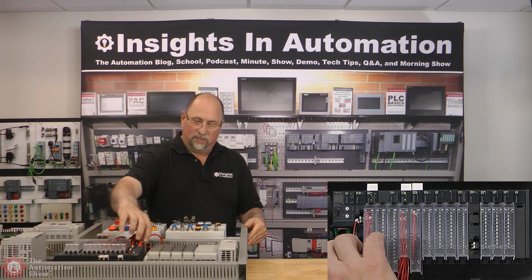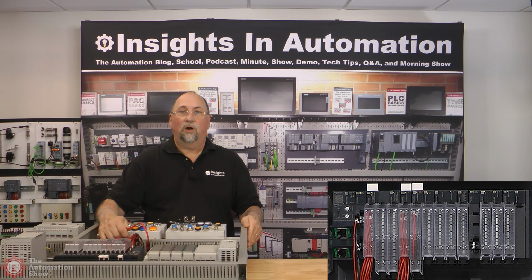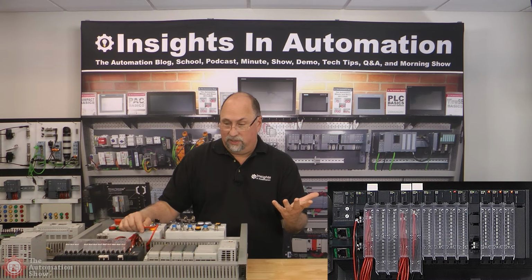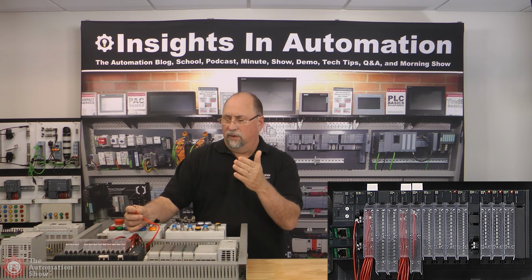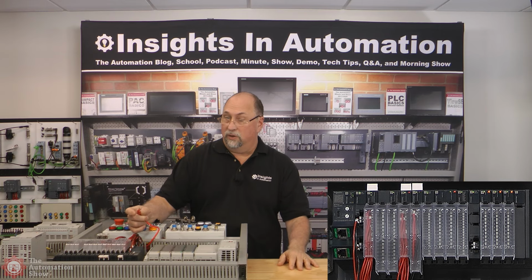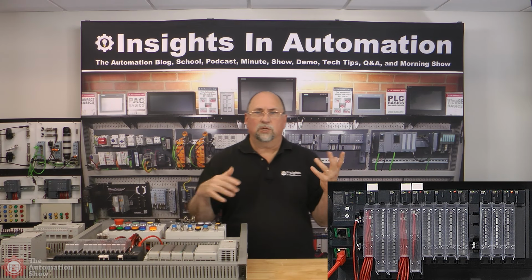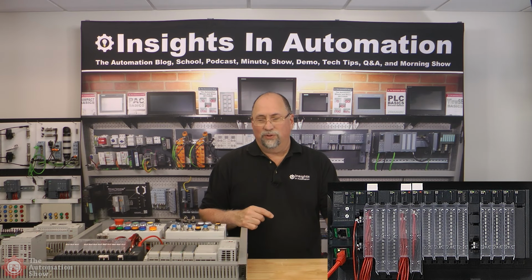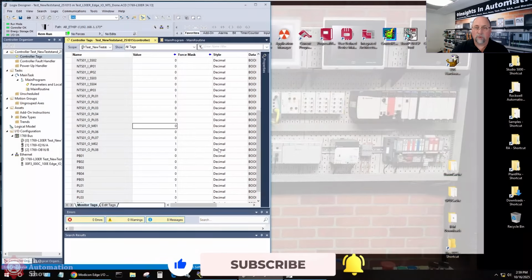And of course, if I disconnected the device, all the outputs go off. It's not holding last state. I did not tell it to hold last state because I don't want it in this case. But you know, that kind of proves that we're going through the Modicon Edge IO NTS. And I'll plug it back in, and in a few moments it should pick back up, and we should see the motors go back on. And when they do, I'll go over to the computer here and I will turn them off. Okay, so just give me a second here.